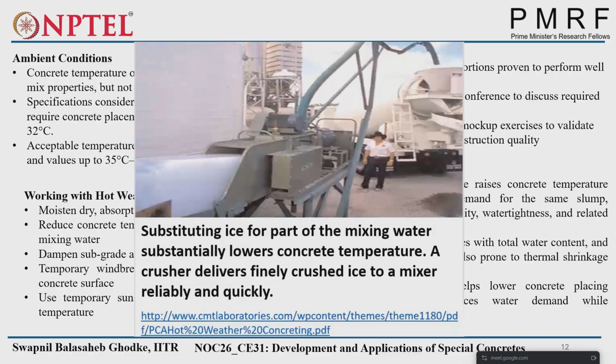That will create a thick hydrated layer, so the unhydrated cement inside will find it very difficult to get water and hydrate after the whole ice melts. Ultimately, the whole cement will not hydrate, but at least the cement needed for the required strength should hydrate, right? So the code doesn't allow using ice directly; that's why crushed ice is used.